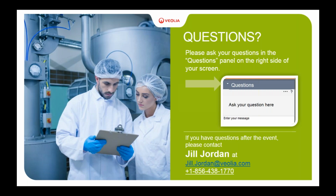Make sure the pump is turned off. I've seen people loosen up a caustic line, forget the pump is on, and then it squirts on them. And it burns.